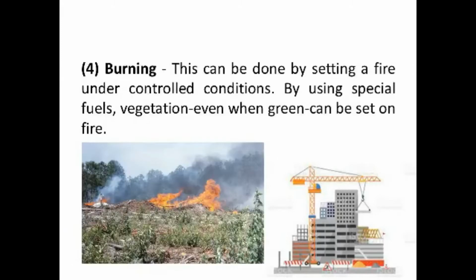Next, we have burning. When the wood cannot be used or the vegetation has to be cleared, one of the best ways para ma-clear yung site is through burning. Burning is done by setting a fire under controlled conditions. By using special fuels, vegetation, even green, can be set on fire. So, after masunog nung area, saka pa lang i-bulldozer to clean up the site.